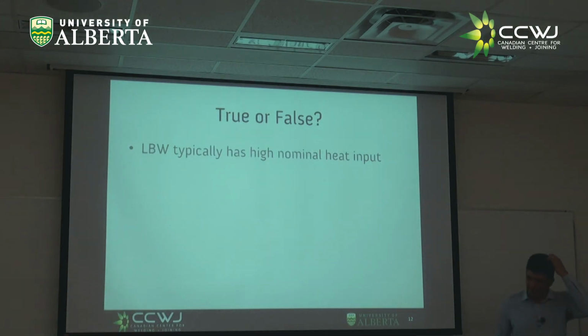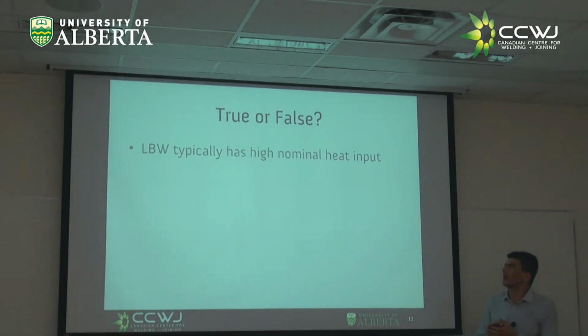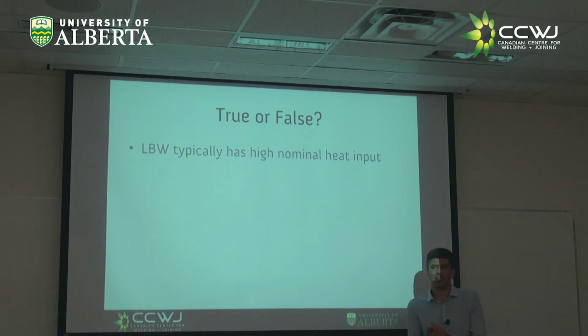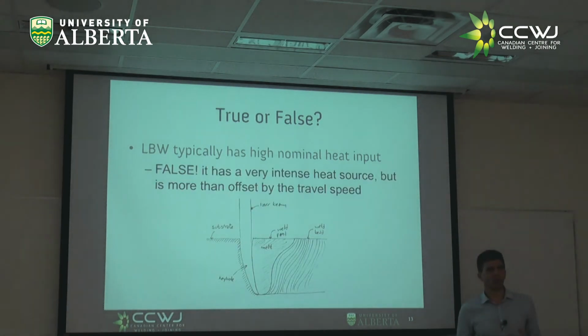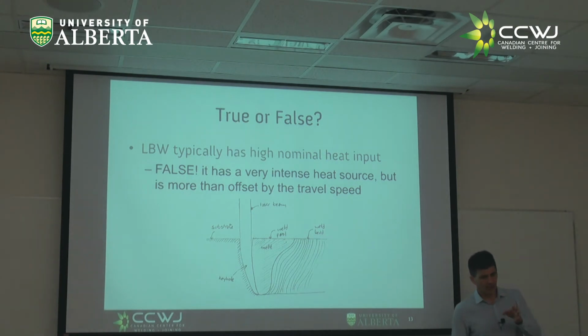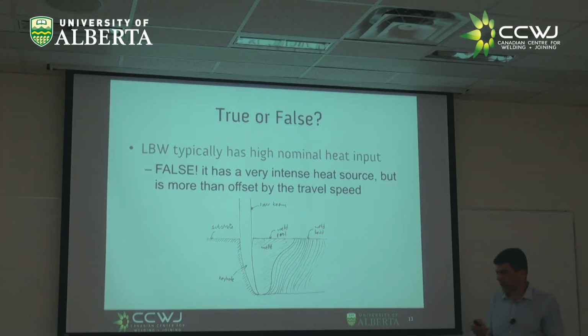All right, lasers. Laser beam welding typically has high nominal heat input. True or false? Thank you. It's false, right? Like what we were saying, it's very intense, but the area is very narrow because you move very fast.